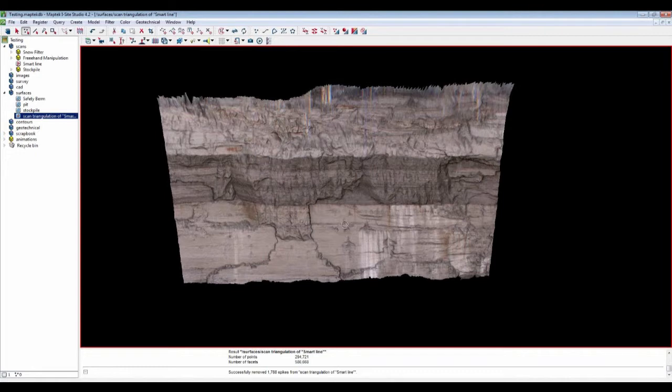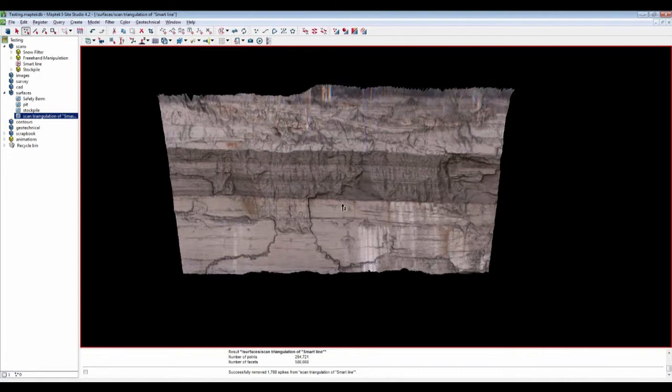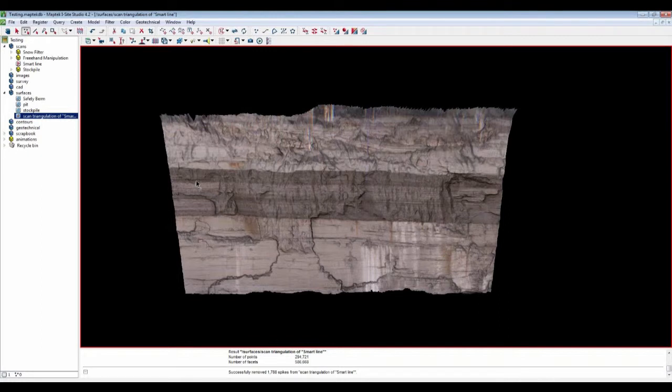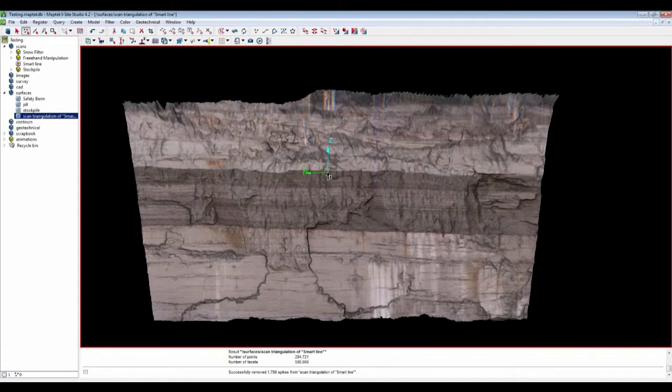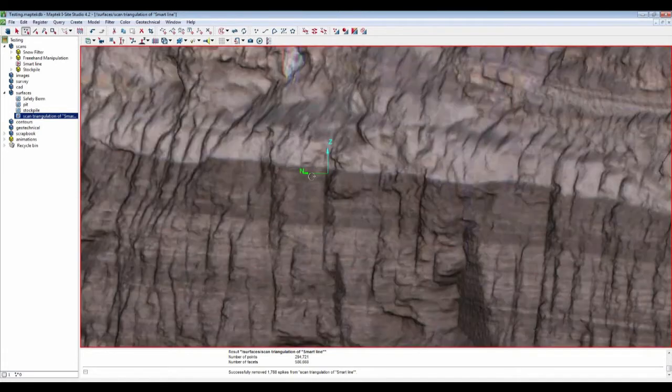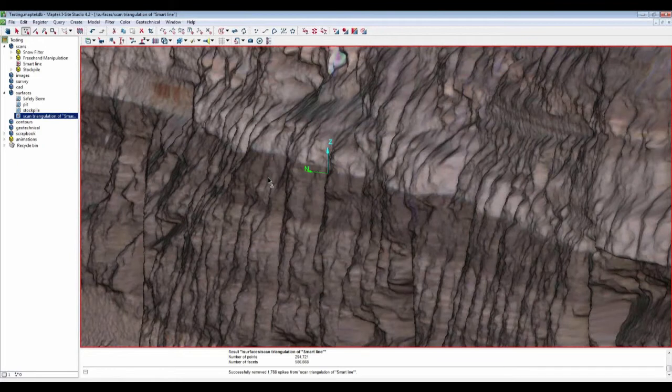And you can see that we've got a really easy to define coal seam right down the middle, and I want to digitize the edge of that. I'm going to zoom in on this for you guys so you can see what I'm talking about. So under the old premise of Smartline, where it's really great at defining edges when there's an actual structural change, this application wouldn't really work. The surface doesn't have a huge dip. There's not a cut into the wall between the coal and the rock. Really, there's no change besides the color.